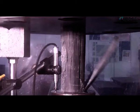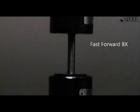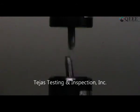Now, compared to this, see another video on a ductile material. This is a tensile test on a steel rod. The first one was the compressive test. I don't know whether you can see the video clearly or not. You see a neck is formed here, and in your solid mechanics or strength of materials lab, probably you have done this experiment. If you keep on increasing the load, a neck forms, but still it has not failed. The deformation is localized at a particular point, and because of the localized stress, this neck is formed. Now you see the neck becomes more prominent, but still it has not failed. Still it has not failed, and it failed.